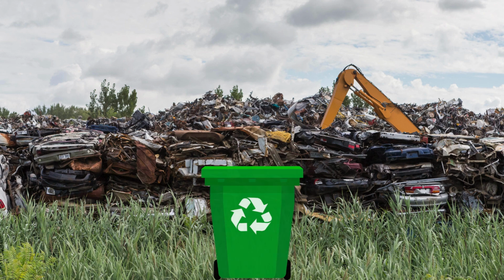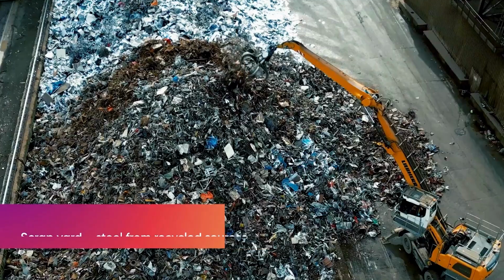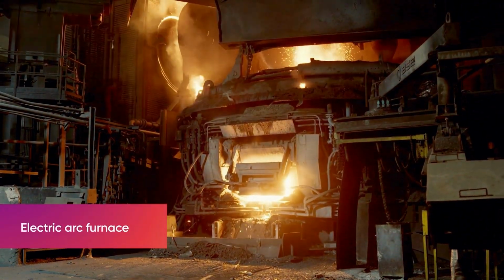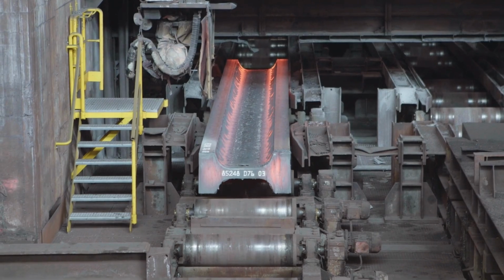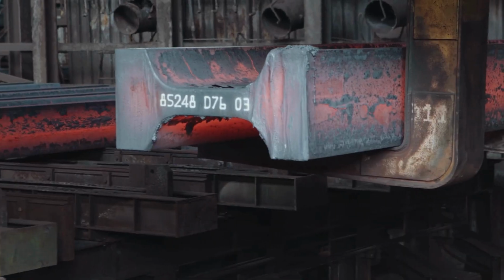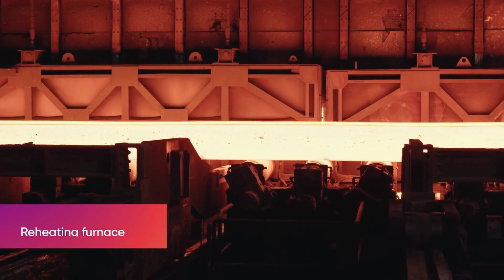Recycling. A913 is made with 98% recycled scrap in an electric arc furnace. Once the scrap is melted, it's cast into a form called a beam blank. The blank is fully cooled and put in storage at the mill until its scheduled roll date.